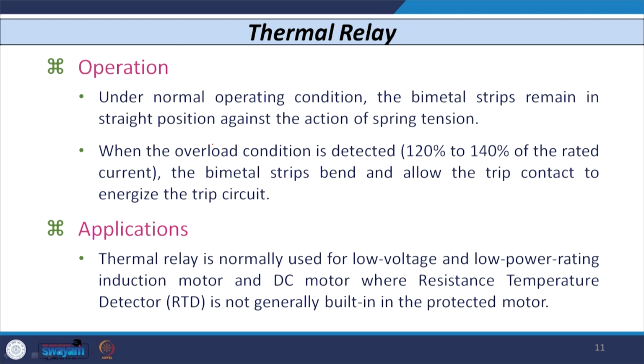So, what is the application of thermal relay? Thermal relay is normally used when a low voltage and low power rating induction motor or DC motor is there, and specifically when this DC motor or induction motor does not contain the inbuilt feature of a resistance temperature detector, there we can definitely use the thermal relay. We can also utilize the thermal relay for protection against overloading in case of generator, transformer, induction motor, and also reactor.